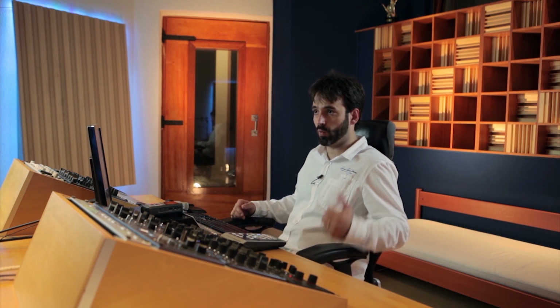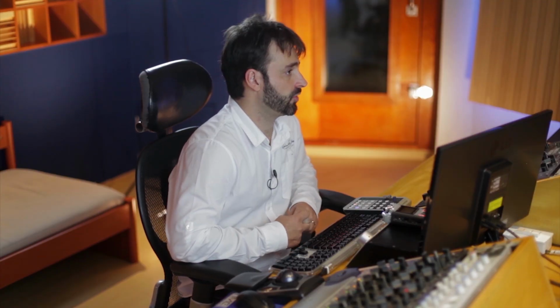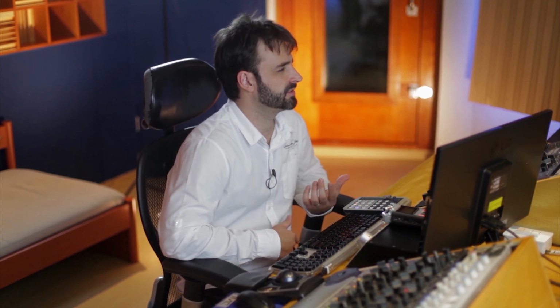In the 1970s, Tom Hidley and Philip Newell began using a room design that Newell presented in 1991 at the AES convention through the article Non-Environment Control Room. In this type of room, the side walls, ceiling, and the bottom receive a large amount of absorption material. The bass traps were reintroduced by Hidley, and since they were big, they could act on low frequencies down to 40 hertz.